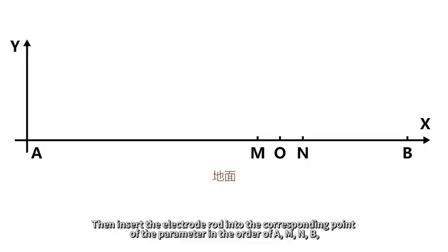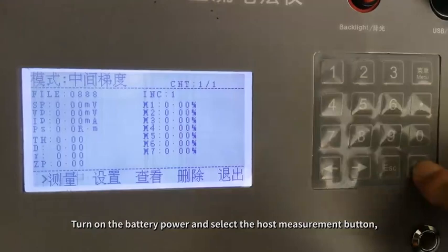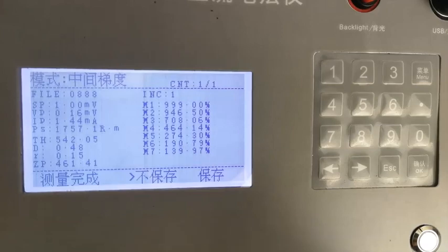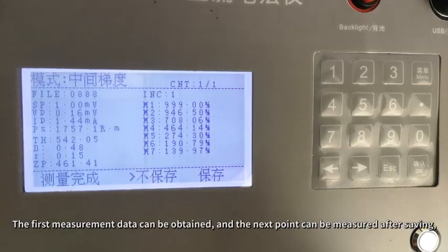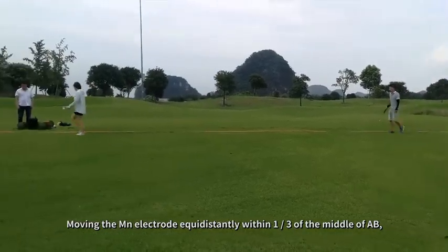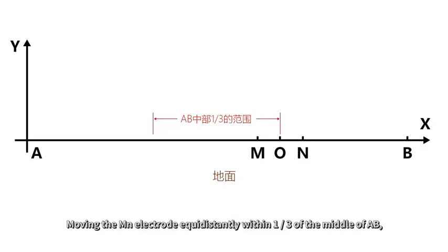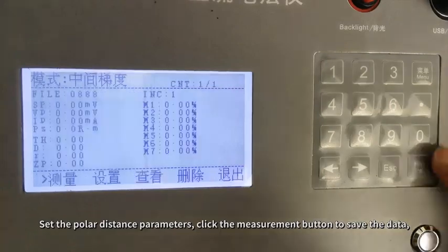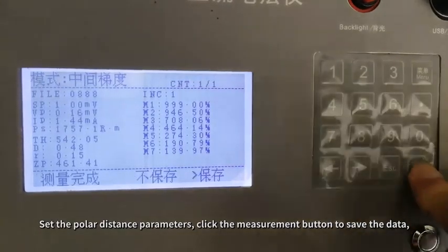Then insert the electrode rods into the corresponding points of the parameters in the order of A, M, and B. Turn on the battery power and select the host measurement button. After the instrument is measured by positive supply, shut down supply, reverse supply, shut down supply, the first measurement data can be obtained, and the next point can be measured after saving. Moving the MN electrode equidistantly within 1/3 of the middle of AB. Set the polar distance parameters. Click the measurement button to save the data.